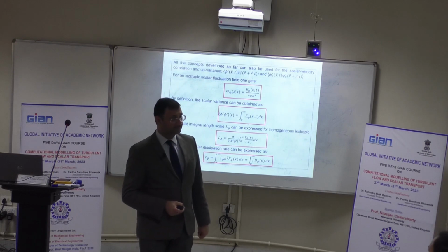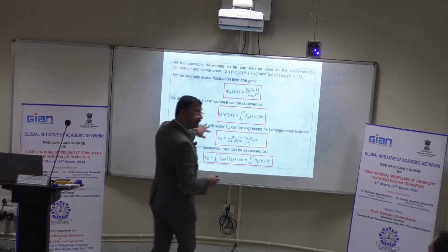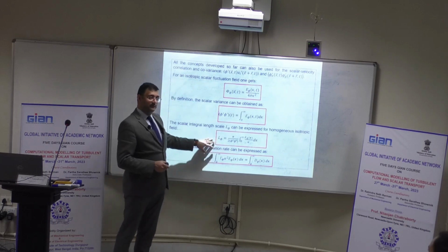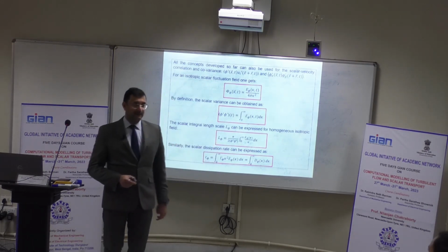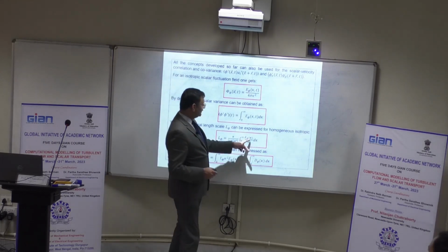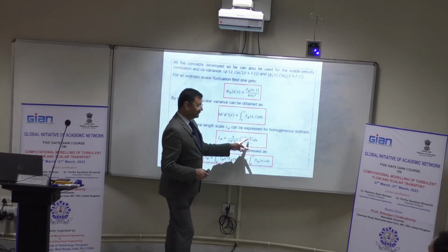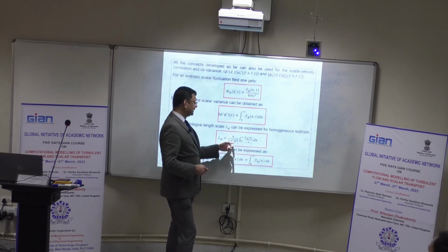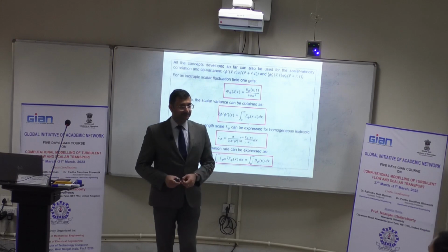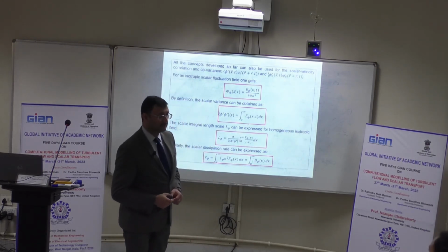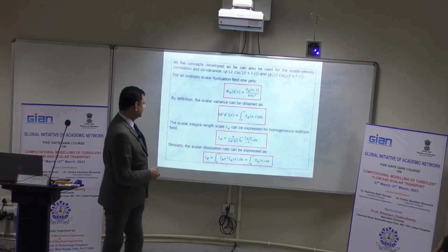The same thing exists for the longitudinal length scale of turbulence under homogeneous isotropic turbulence. Effectively, here it is going to become the turbulent kinetic energy spectrum. Here it will be U prime. Basically, it is going to be the kinetic energy part. Ui, U1 prime, U1 prime. Right?